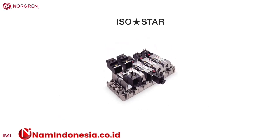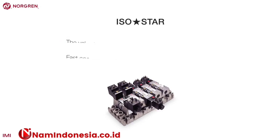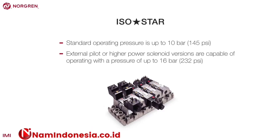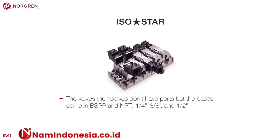The valve has a glandless design offering a very long life, with fast, accurate, repeatable switching time through its lifetime. Its standard operating pressure is up to 10 bar or 145 psi. But the external pilot or higher power solenoid versions are capable of operating with a pressure of up to 16 bar or 232 psi. The valves themselves don't have ports, but the bases come in BSPP or NPT, 1/4 inch, 3/8 of an inch, and 1/2 inch sizes.